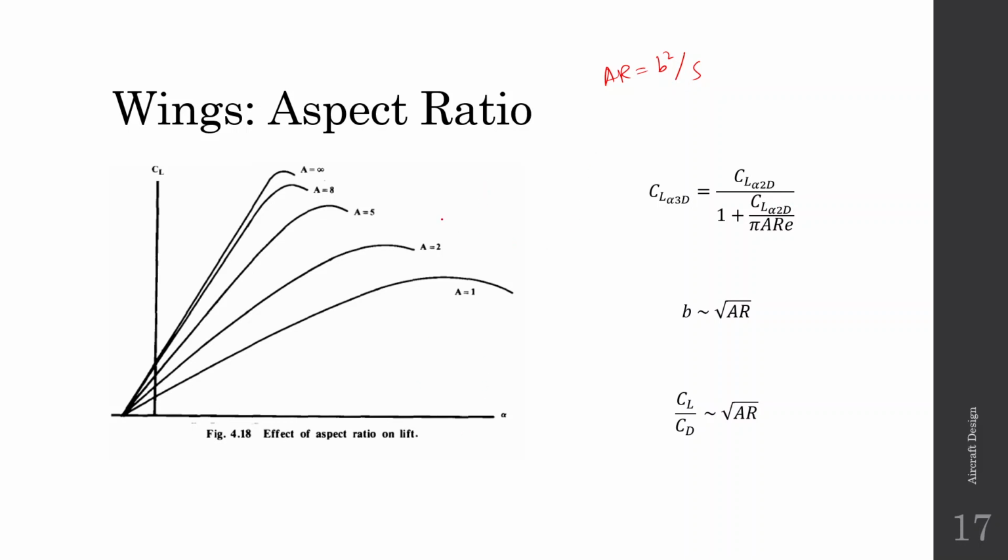Essentially, if you have a finite wing, like this aircraft with a finite wing, then towards the tip of the wing, if you look at it from the side, below the aerofoil we have high pressure and above the aerofoil we have low pressure. Because of this reason only there is an upward force. We have low pressure at the top and high pressure at the bottom, and because of this there is an upward force on the wing.